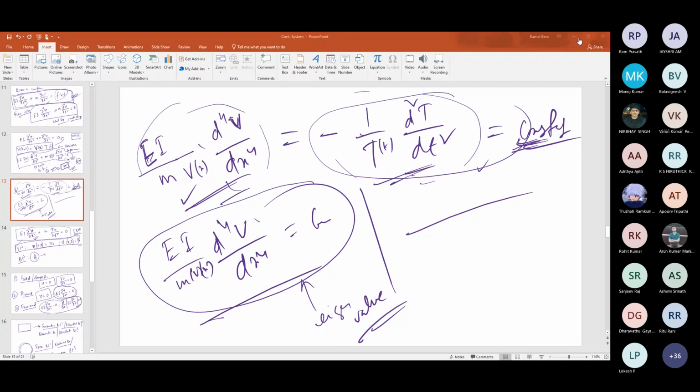So what we have discussed today is the formulation of the equation of motion of an Euler-Bernoulli beam undergoing transverse vibration. And then we talked about different boundary conditions and how to solve that boundary initial value problem. So the technique of variable separation, we just started it, and I have given some idea. Then we will proceed ahead from this, and for at least two examples, like a cantilever beam and a simply supported beam, we'll try to find out the natural frequencies and the mode shapes.